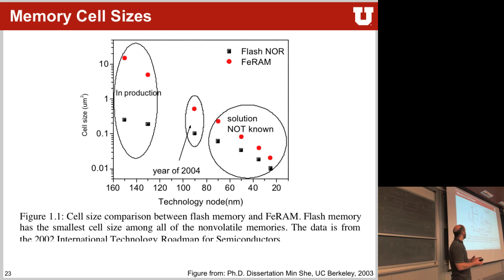So what could be some of the implications of that? What if the cell size is, for example, let's take this example here, about 0.1 micrometer squared versus about 5 micrometers squared? What are the implications of that? Longer distance, less memory density, right? If your memory cell is 5 times bigger, then you can have less memory on the same chip area.